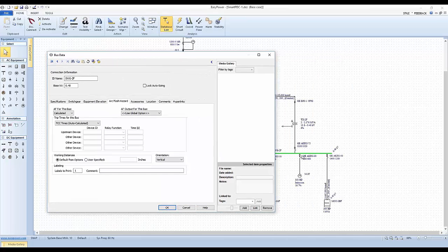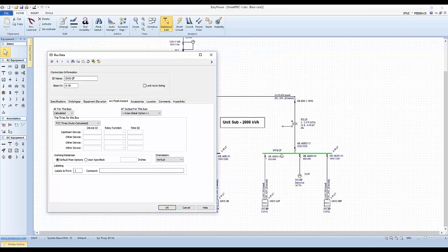And as I look at this particular bus, if I physically go out and look at it, if I open up the panel cover for the switchgear, I see that this main feeder breaker, the main breaker coming into it, is in my direct line of sight, and I'm physically exposed to the connecting points, the cables coming into the main breaker. For me to work on this bus, switchgear 2F, to do any hot work, I cannot count on this breaker's trip settings to protect me and thereby reduce the amount of energy that I'm being exposed to in the case of an arc flash.